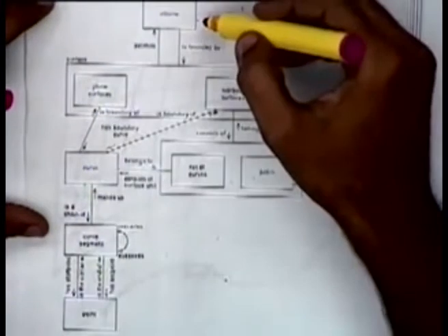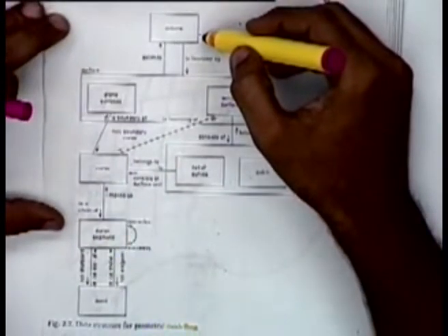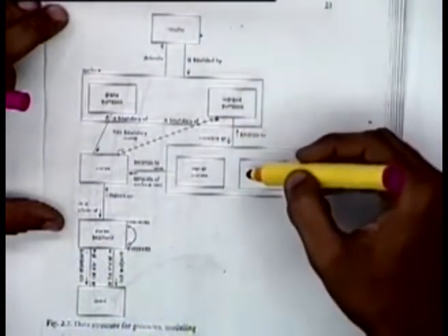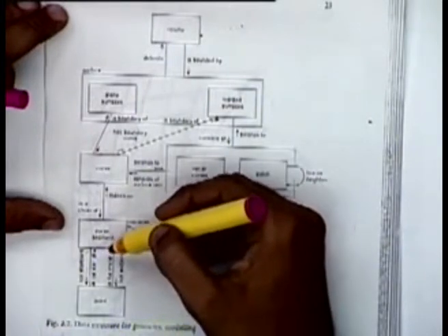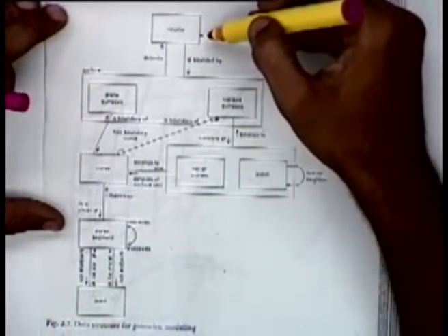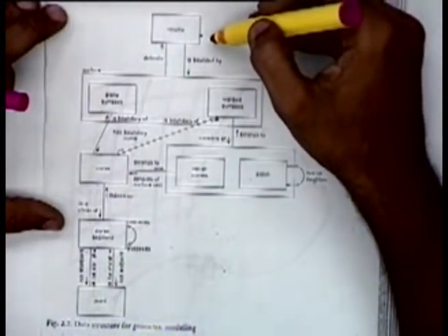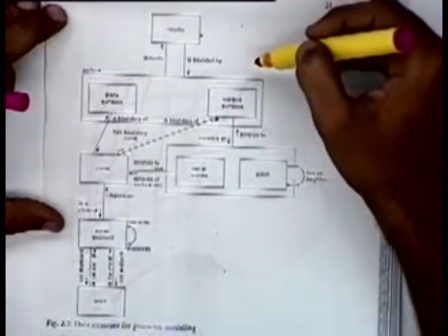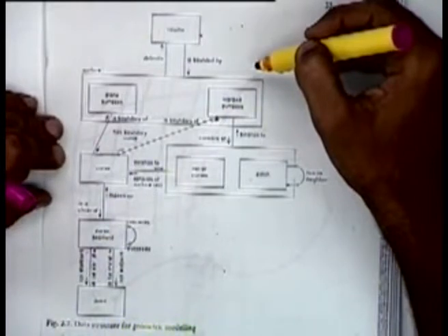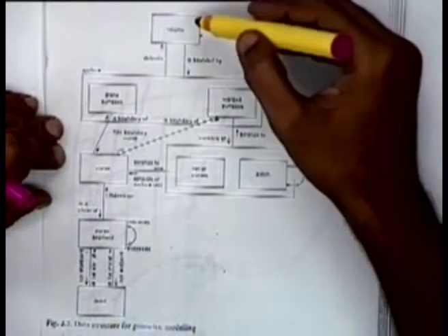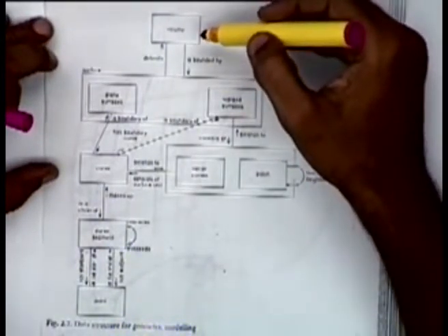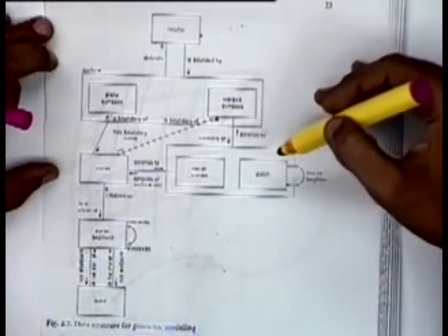So if we want to represent a solid or a volume, this solid or volume will be represented by surfaces, which are represented by curves, which are in turn represented by curve segments, which consist of points. If we have to describe solid modeling techniques, we cannot describe them unless we have some idea of how to represent curves and surfaces. The basic method of representing any solid will always have methods of representing curves and surfaces embedded in it.